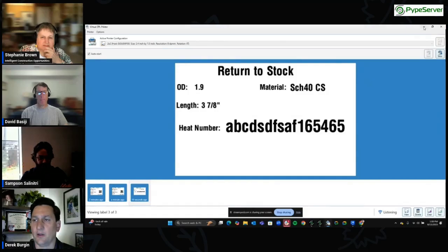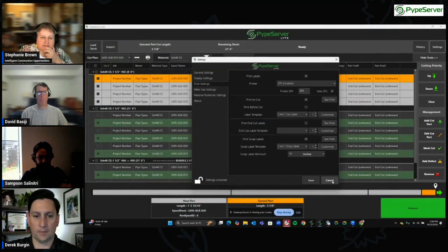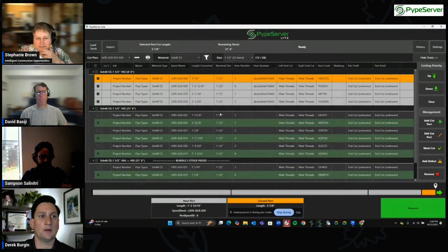So keeping track of all that information is key, especially when those heat numbers get cut off, because if anything were to happen, catastrophic failure, you want to be able to go back to your PVF provider and say, hey, this is a batch that had a failure to it.